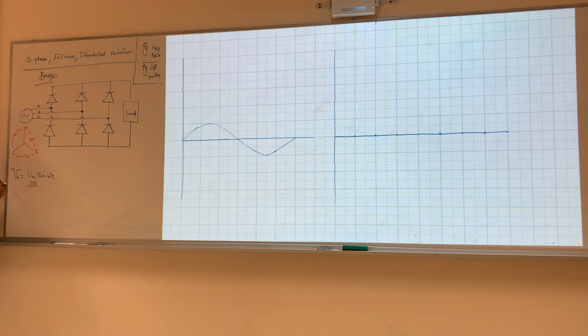I want to make a note, guys. If you see a V source like this, and you see V equals Vmax times sine omega t, the value that you see here is Vmax. Let's say if it's 120, then Vmax equals 120. You don't have to do the calculation times square root of 2, all that.